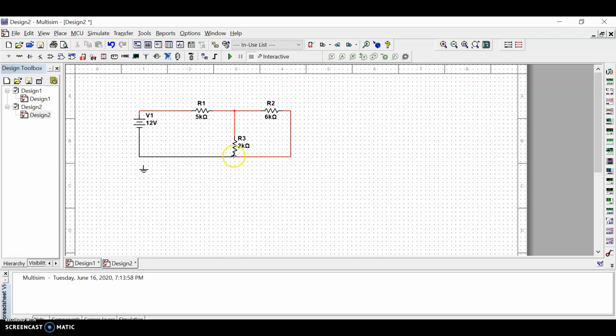Okay, it doesn't want to stay. You have to be careful so it stays there. Okay, and then you can make it look nicer. Then you have to connect the ground, because a power voltage source doesn't mean anything. It doesn't have a reference. So in this case, we said we are referencing to the ground. So it's 12 volts above this ground, which is 0.